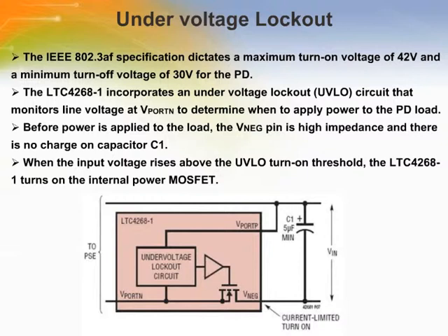The undervoltage lockout pin also includes a bias current allowing implementation of hysteresis. When undervoltage lockout is below 1.24 volts, gate drivers are disabled and the converter sits idle. When the pin rises above the lockout threshold, a small current is sourced out of the undervoltage lockout pin, increasing the pin voltage and thus creating hysteresis. As the pin voltage drops below this threshold, the current is disabled, further dropping the undervoltage lockout pin voltage. If not used, the undervoltage lockout pin can be disabled by tying to VCC.